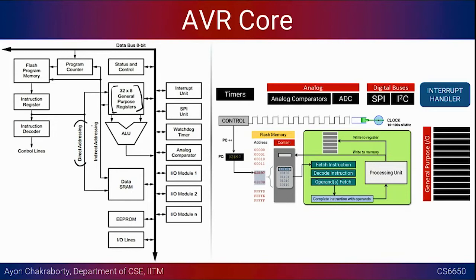The way the data is fetched, there is something called direct addressing and something called indirect addressing. This is basically whether you are fetching the data directly from your memory or going via registers. If you are going via registers, the registers sometimes store your address, and in that way you indirectly fetch the data. So I would request you to look at them. It is for your knowledge.